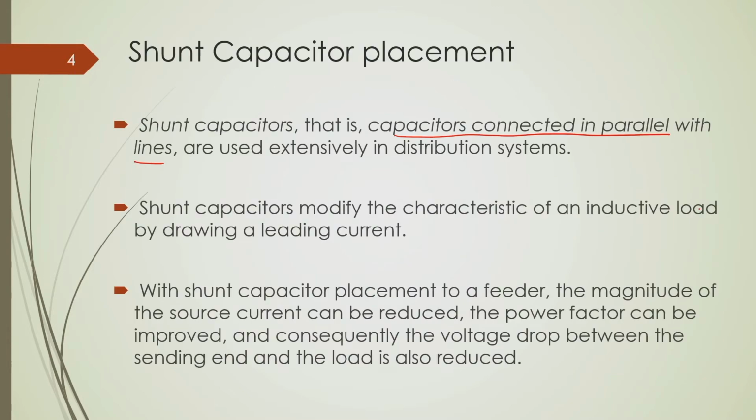Okay. Now, as I said, these shunt capacitors modify the characteristics of an inductive load by drawing a leading current. Okay. Leading and lagging current are confusing, but you can understand that whatever the inductive load operation we have, exactly the opposite, complementary operation we will get by using capacitors.